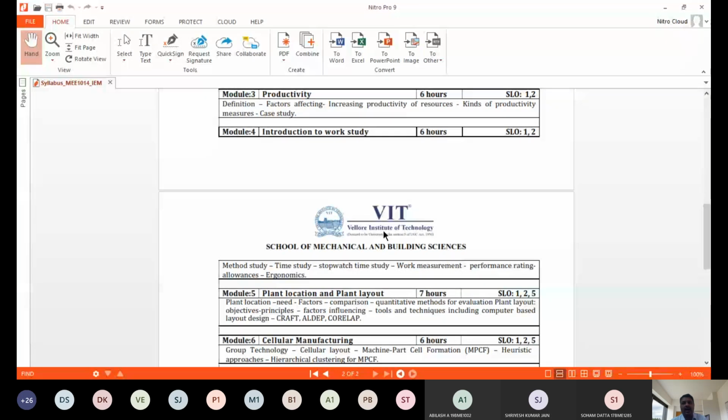Suppose I want 1 lakh pens in a particular given duration of time. What is the expectation from your worker? You cannot ask everyone to work at a very top high level of efficiency. The skill level will vary from person to person, but you cannot leave it without asking them, considering this fact. So you have to demand, gentlemen, you have to produce so many pens per day, then only in an 8 hour shift have you done a reasonable amount of work for the salary that I pay. You should be able to tell them. For that, you should know the standard time that it will take for an average person to do the assembly. You can expect average performance from any worker. Anything above, you can appreciate; anything below the average performance, you can penalize or do necessary counseling and ask him to perform well.